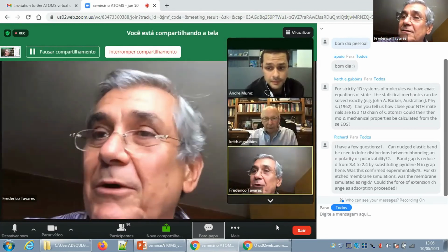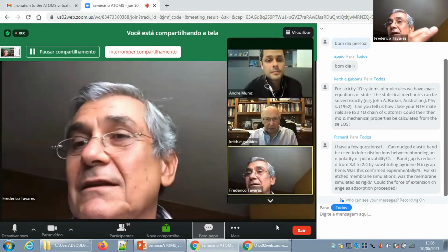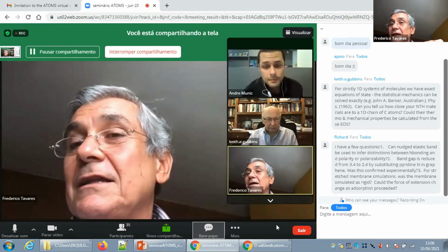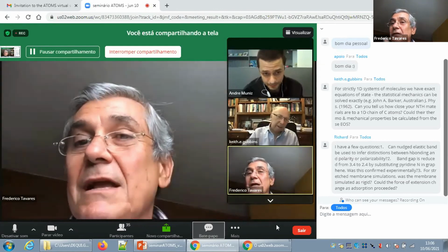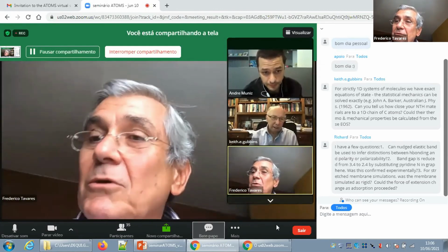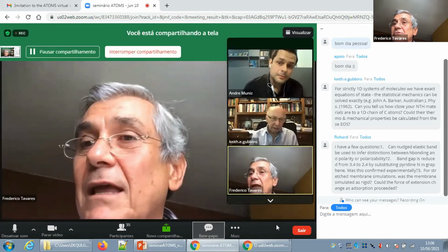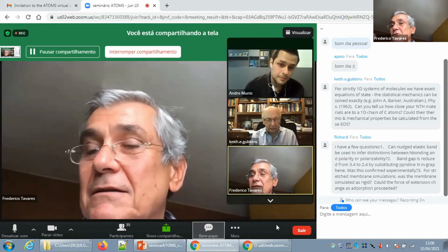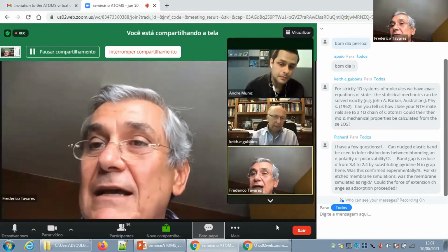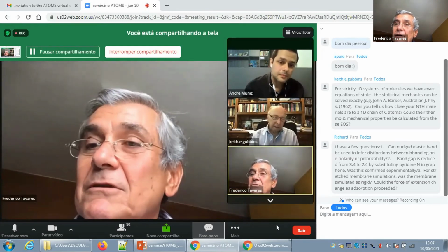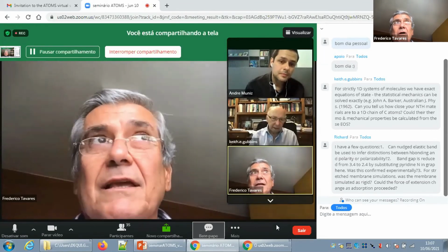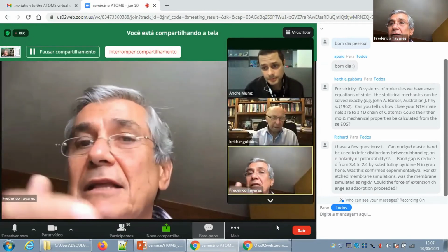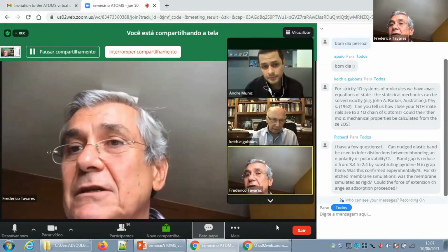It's easy to separate these two components at very low temperature, like minus 100 something. It's very easy doing cryogenic separation, but at normal temperature, it's very challenging to separate methane from nitrogen, because the van der Waals interaction is very similar at normal temperature, and also the sizes are very similar. So it's a very, very tough problem, and even better if you could get the nitrogen, adsorb nitrogen preferentially over methane.